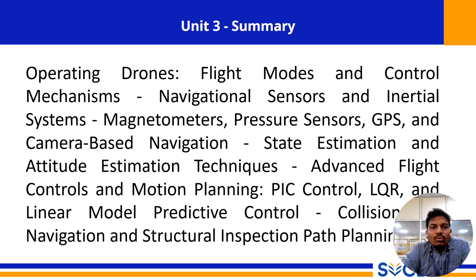The building block of these loops is typically the PID controller, a robust compensator that adjusts its output based on the proportional, integral, and derivative of the error signal. While PID is a powerful and widely used tool, more advanced flight controllers are also available.